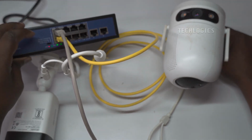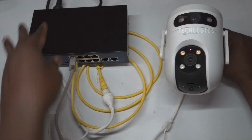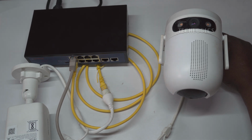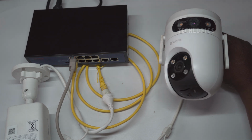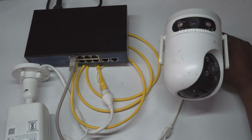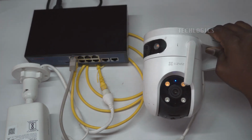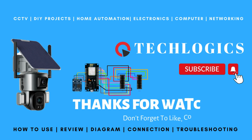The PoE splitter acts as an intermediary, dividing the incoming power and data into distinct outputs for devices that do not natively support PoE. The PoE splitter provides two outputs, a LAN port for data connectivity and a DC output for power. Connect the LAN port from the splitter to the camera's Ethernet port to enable data transfer. The DC output should be connected to the camera's power input to supply electrical power. This configuration ensures that your camera receives both network connectivity and power through a single cable, simplifying the connection process.